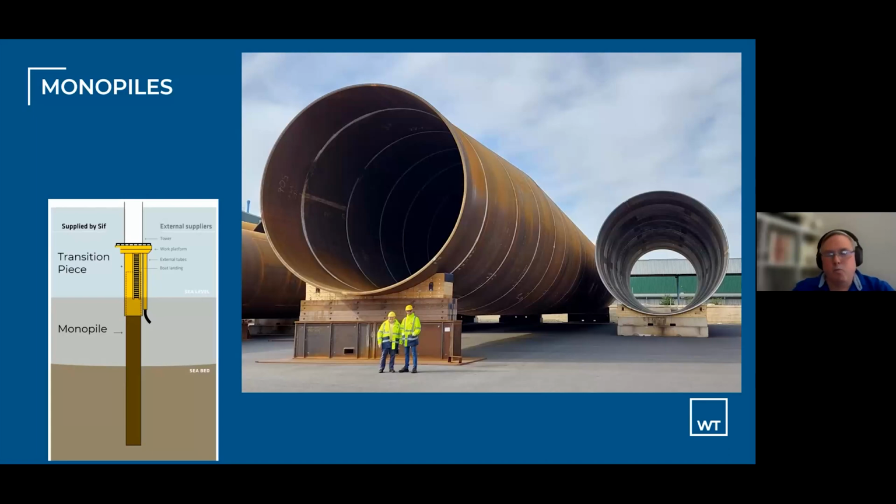Monopiles are, and will remain for some time, the most common structure. I'll quibble a little bit, Kim, with the water depths. We're doing monopiles in depths up to 60 meters, especially with the larger turbines. Jackets, you can probably go to 80, possibly 100 meters, and then beyond that is where you need floating.